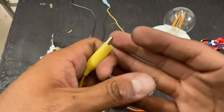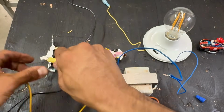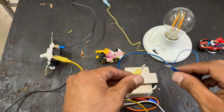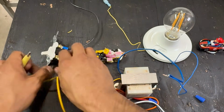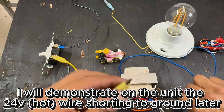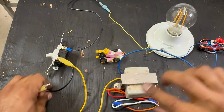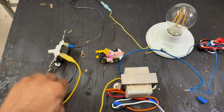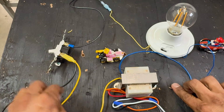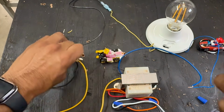If it has a built-in fuse or a fuse popper or a little fuse, a 3-amp fuse will go bad. But yeah, typically there's two types of shorts: a short to each other, right? Where they saw each other before they made it to the rehab center and they're fighting. Or because now my common is grounded to the metal. Let's say, because of a vibration, it exposes the copper and now it's touching the metal. Well, it's the same thing as if it's touching common, right? Hot is touching common because it's grounded, and you'll see that on the unit. But do you get the point, right?